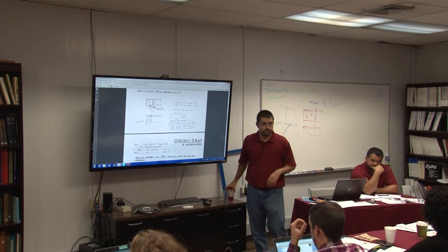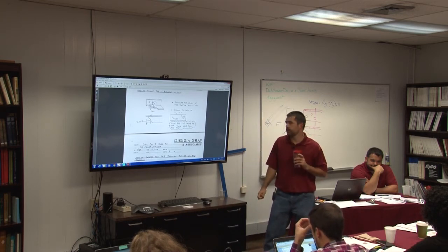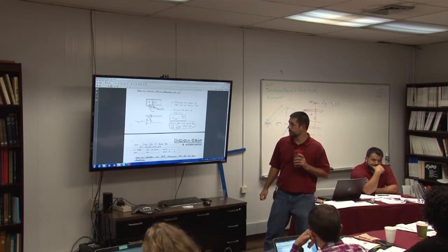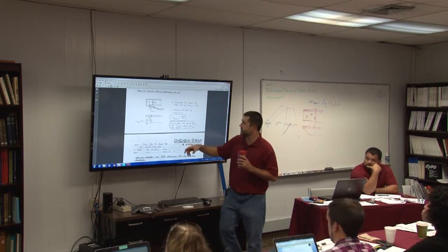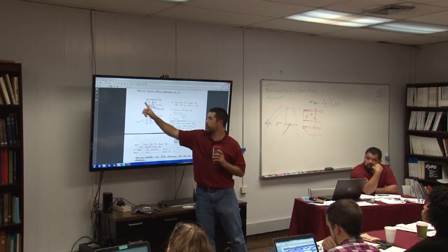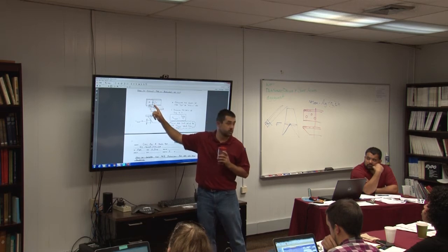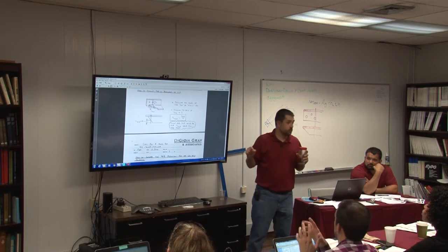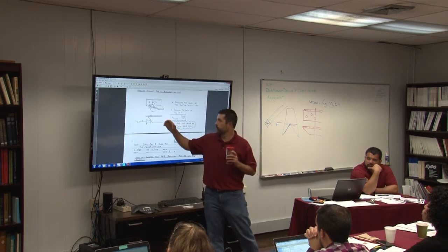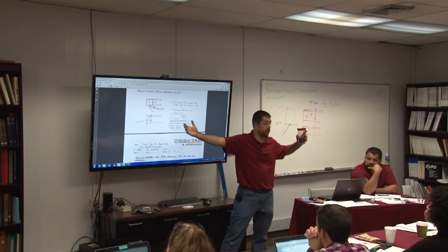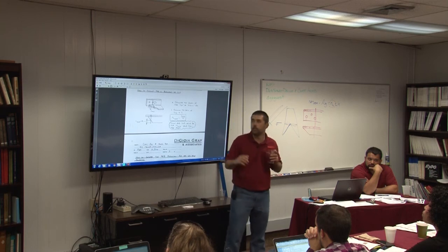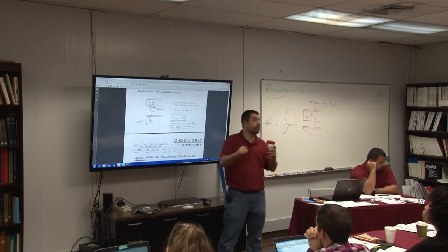What's probably more common is that full clip. That's right. But a lot of those are on redundants. That's not a tremendous issue, but it's something to be aware of. Is that why you are not accounting for the other bolt? That's correct, because the idea is, let's say that this has got 20 kips in it. You assume that you got 10 kips in each bolt. So if I got 10 kips in this bolt, then this section sees 10 kips and this section sees 20. To really fine-tune, sharpen your pencils, maybe I should check this for 10 kips and this for 20. But in my mind, what I'm really concerned about is the member snapping in half and no longer being connected. Whereas if I started to lose some strength here, maybe it transfers some strength to the other bolt. I'm mostly concerned with the end of the connection where it sees the full tension.